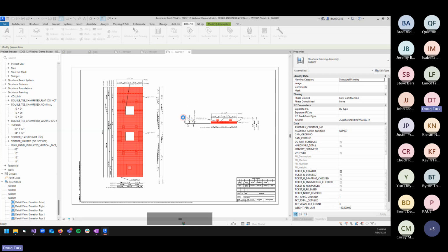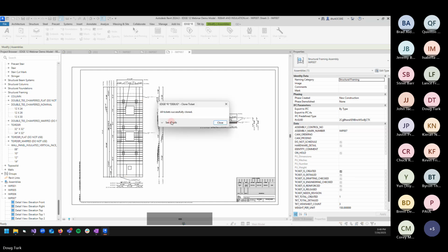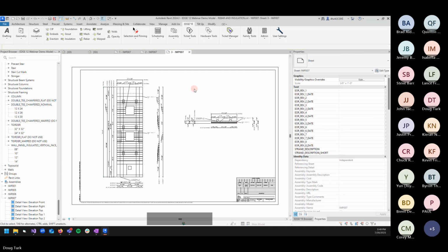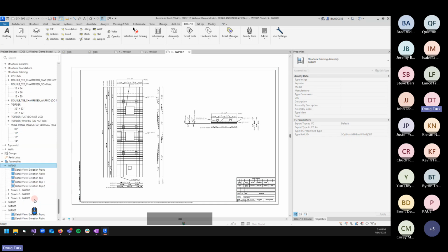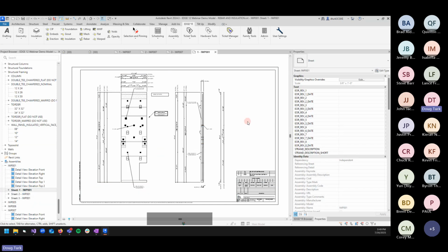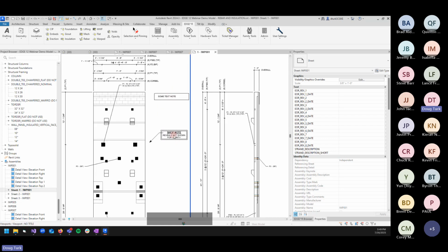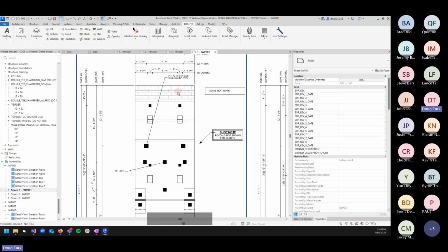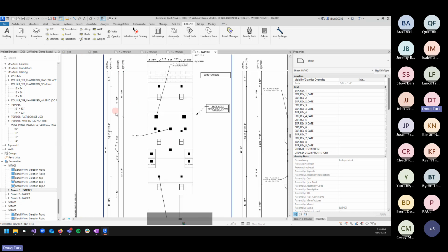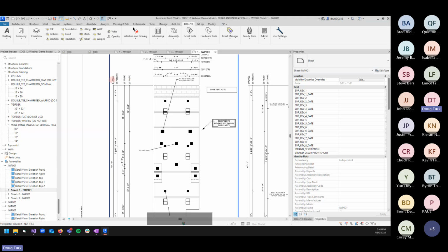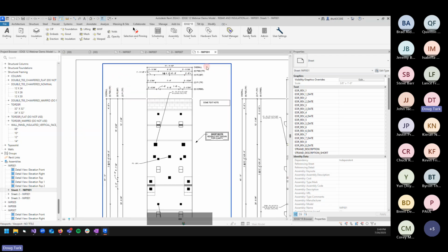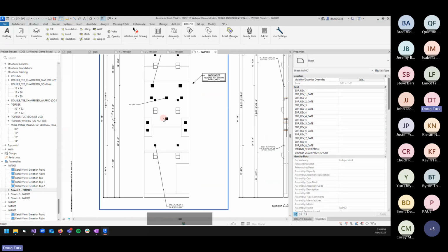Give it just a moment. Perfect. And now we can hop over here and take a look at what it made. So this is our sheet one. Again, we're seeing those annotations that we brought in coming through. We're seeing these different tags coming through in the same location that they were. Any matching hardware is dimensioned in the same way as it was in the source, but counts are updated to reflect the piece that we copied to. So there is intelligence behind these to make sure that any text that's associated with a dimension is being brought through and updated to what we're actually bringing it to.